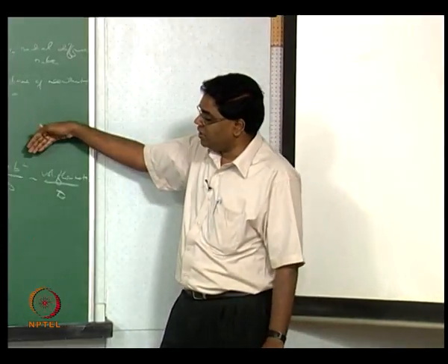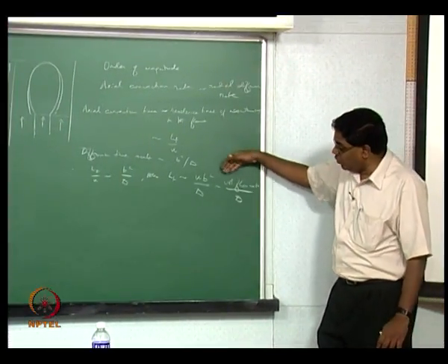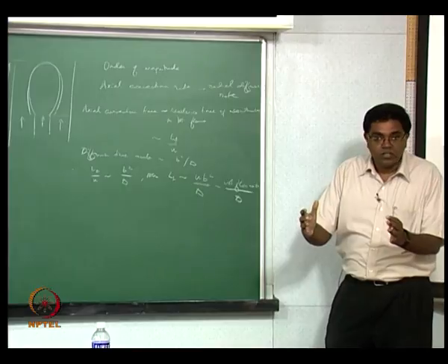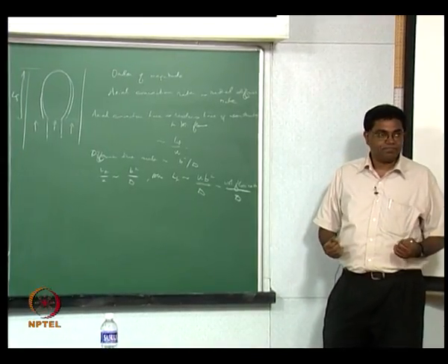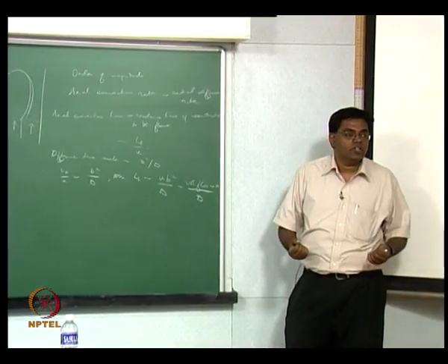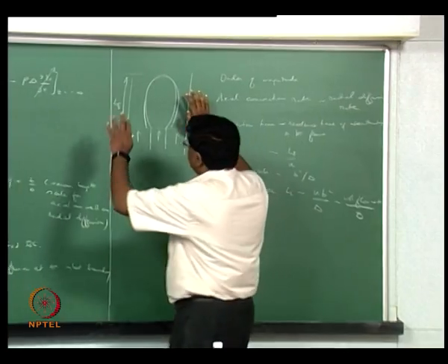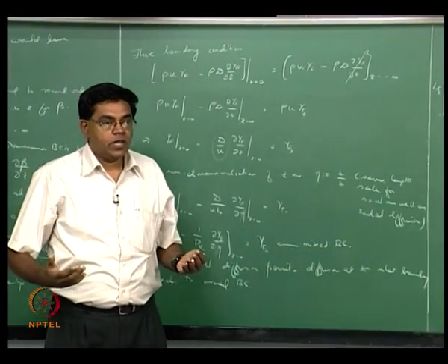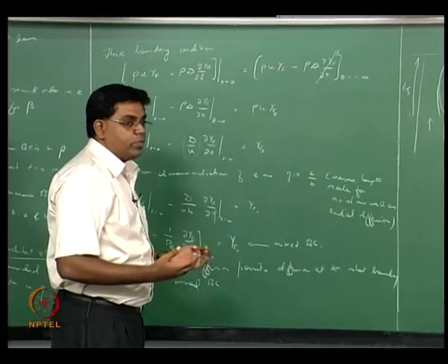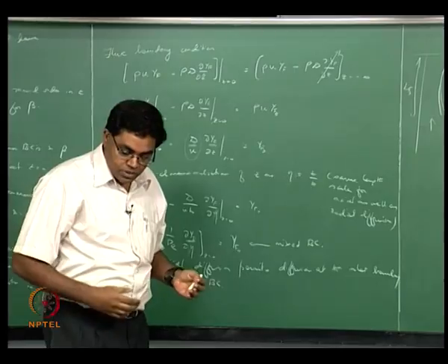The reason is that as we keep on increasing the velocity, or the volume flow rate, or the duct diameter, at some stage we get into turbulent flows. And then what happens? If you now have turbulent flows, the diffusion that happens is going to be turbulent diffusion, and there's not going to be molecular diffusion anymore. So we have to factor in the turbulent diffusion.